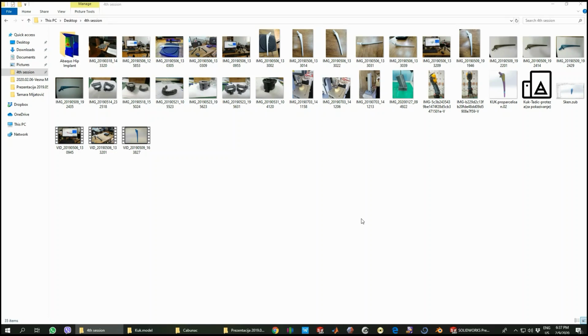We've shown you how 3D prints look like in the second session and how you post-process your models. If you remember, for FDM technology we had to remove a raft and supports, and with SLA technology, because it uses liquid plastic, they call it resin material, we had to rinse models in isopropyl alcohol in those two vessels. Then after rinsing them we had to cure them with UV light in a chamber.